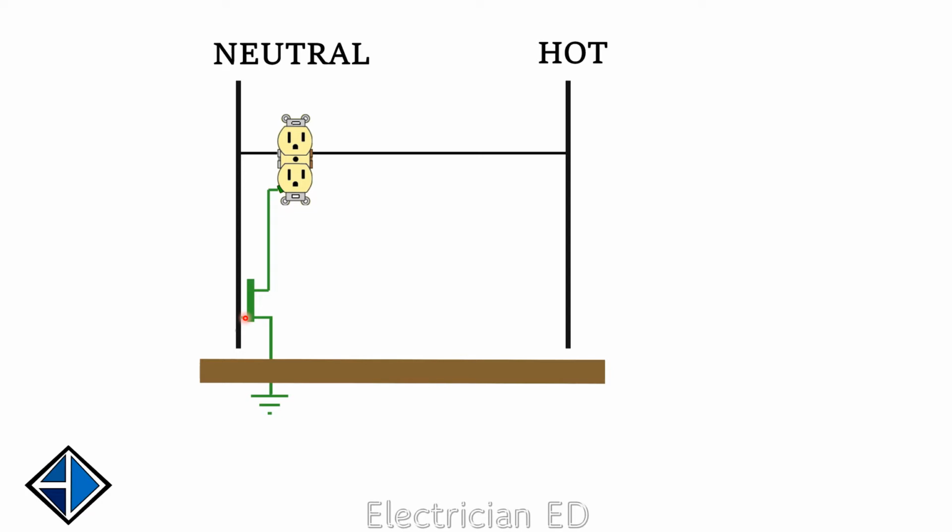However, it has to have this little connection at least one time so that it will be an effective ground fault current path back to the source. If we didn't have this, then the earth would have to carry all of the ground fault current back over to the pole and back up. And some of that will happen, and you'll see that later on in the video.